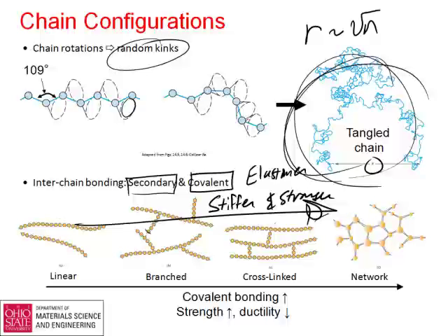Most of our undergraduates, a lot of them don't get it by the time they graduate. It's a point we repeatedly hammer. But stiffness is resistance to elastic deformation. Strength is resistance to permanent deformation. These will primarily get stiffer as you go along.